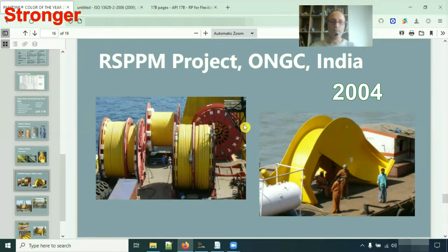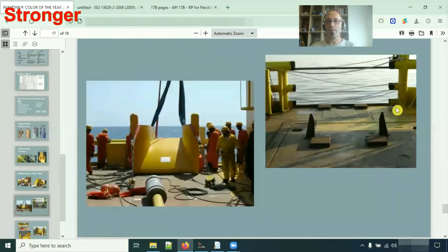Here you see the flexible pipes are transported on the reel on board of the vessels that we used for laying. Since the vessel we had was not a flex lay, we designed and manufactured the chute that you see here. The chute is transported on a flat top barge. And in the meantime, the location that we considered for the installation of the chute is prepared. We did these cuttings and welded these stiffeners and prepared it for the installation of the chute.